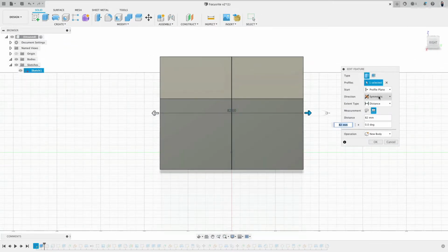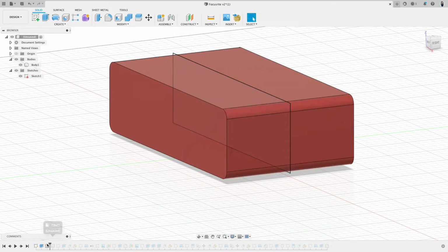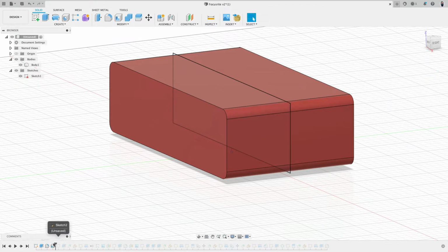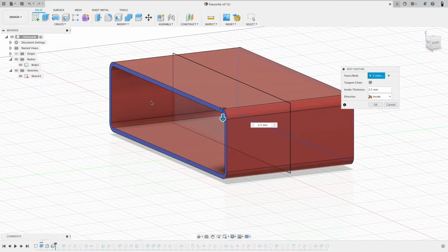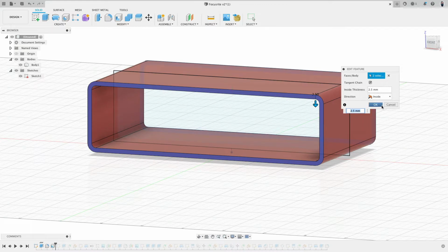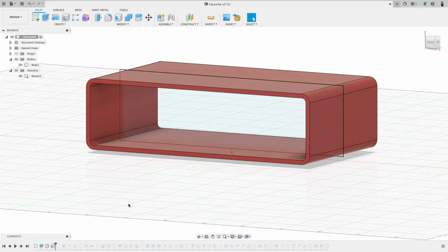going 82 millimeters symmetrical for the whole distance. So 82 millimeters whole, 50-50 forward and backwards. Then I can round these edges by 5 millimeters. Simple G1 is fine. And now we will select the two front and back faces and then shell it by 2.25 millimeters. So now I have actually an extruded aluminum casing, and I can start constructing the next element.